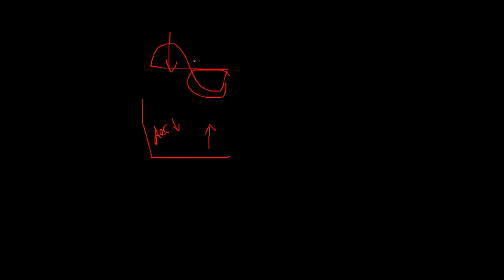So when it reaches this zero point, the velocity of the electrons will be the same. The electron which comes with lower velocity will be accelerated, and the electron which comes with higher velocity will be decelerated. So in the drift space, the electrons will be bunched at a particular point, then travel to the catcher cavity. Here it produces a low power microwave signal.